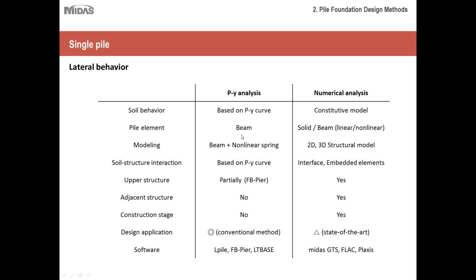Then for pile elements, under PY analysis we use beam, whereas in the numerical analysis you can use a solid or a beam member, and this beam member could be linear as well as non-linear. By non-linear we mean that you can also model the non-linear behavior of the steel or the concrete that is being used as a material for the pile. And this goes to increase the accuracy of the analysis and more accurately represents the realistic scenario.